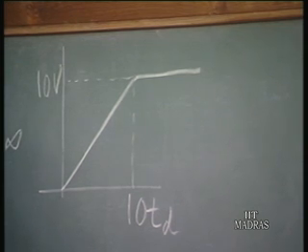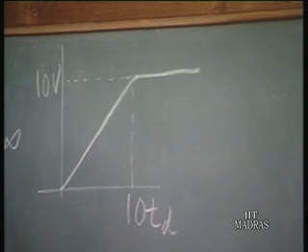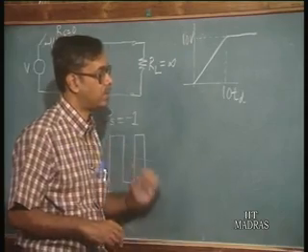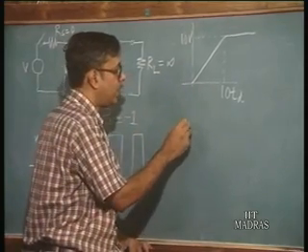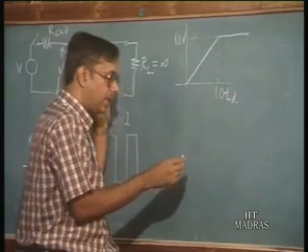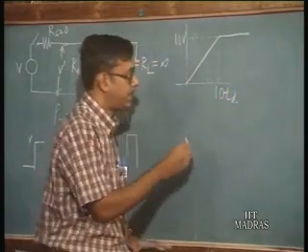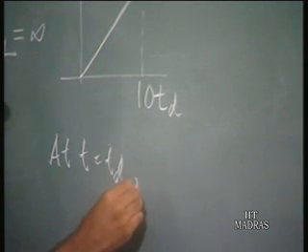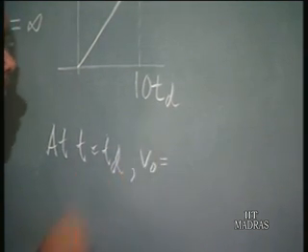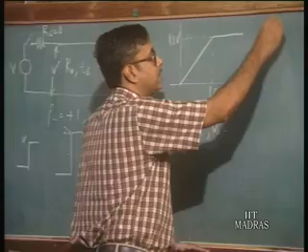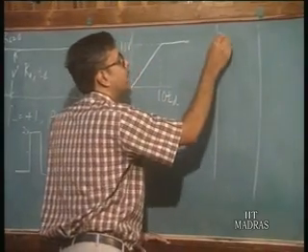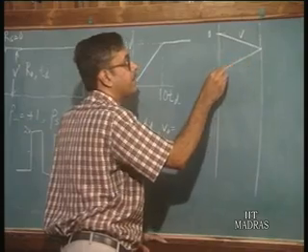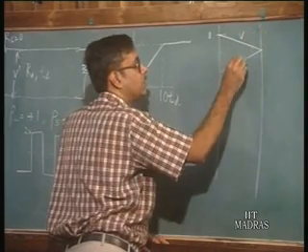Now, if we have such a waveform, and if we still have the same conditions, that at the load end it is open circuit and at the source end it is short circuit, what is the output waveform? Let us look at it. Again if we take the same diagram, at time t equal to TD, what we have is the output voltage equal to, of course, let us draw this diagram. If this is 0, and you have a voltage V here, rho L is plus 1, so you will have V.